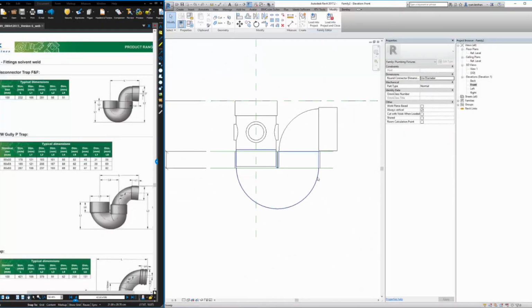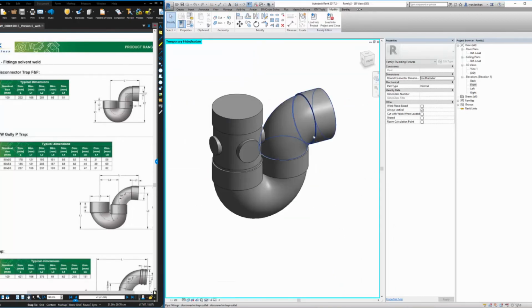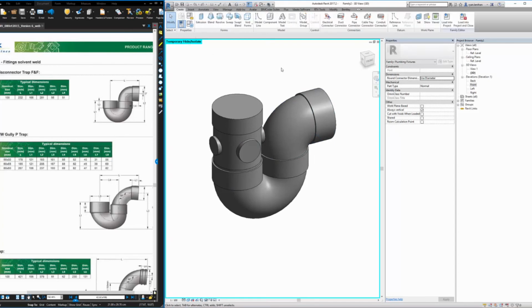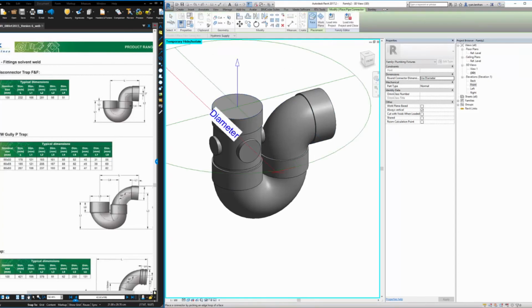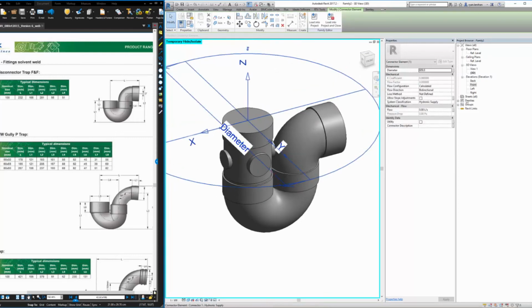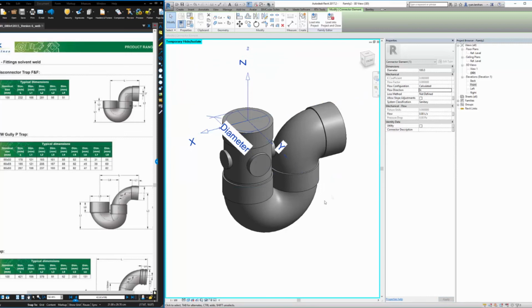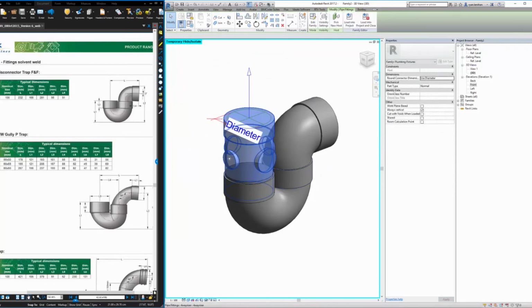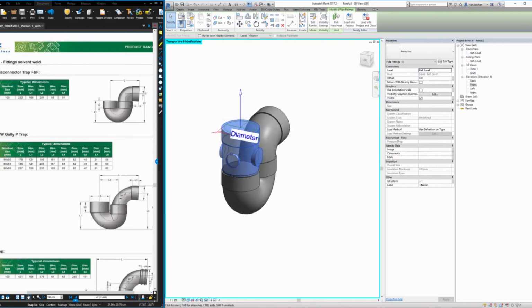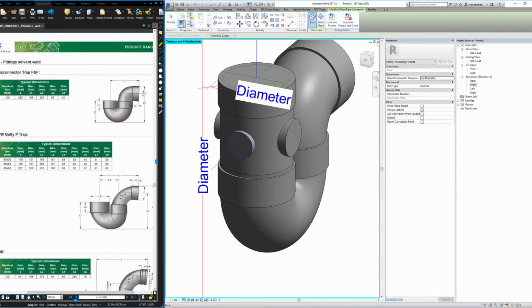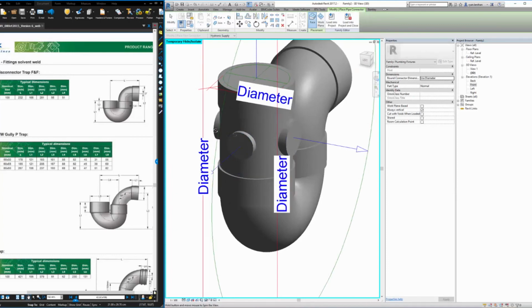So once you've tested the flexing of all the parts in the floor waste, the last thing that we need to do is add pipe connectors. So the way that this family is built is it's designed to have a pipe connector come out of the top. Originally, I used to have the four-way riser extend right up to the slab, so you could drop the trap by up to 1 meter. But that's not actually technically correct. So you'd actually have the pipe coming out through the slab, and then that would drop 1 meter before it hit the four-way riser. So that's why there's that pipe connector on the top.